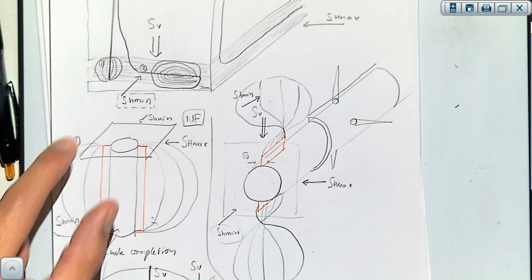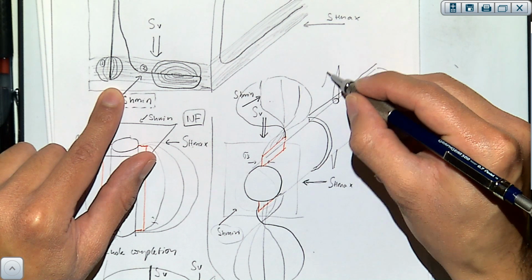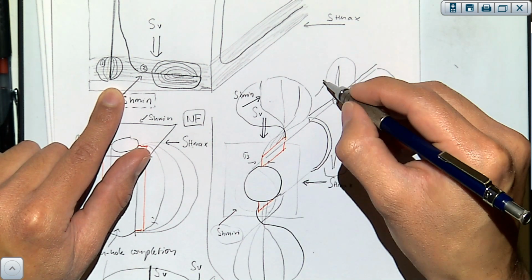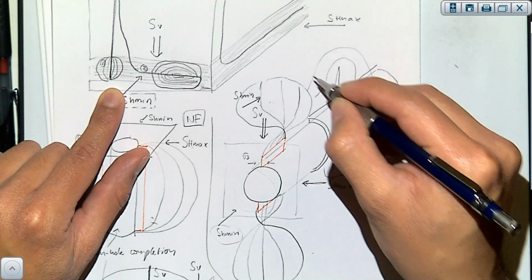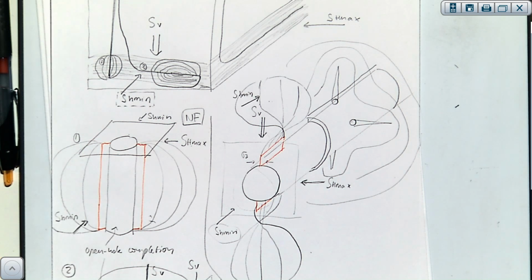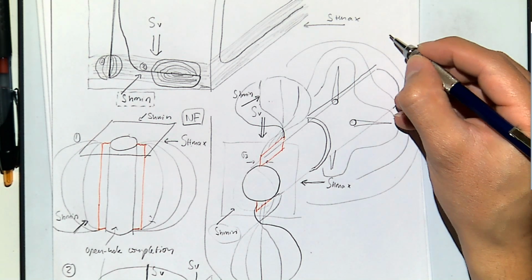So by having these perforations, a hydraulic fracture that may start something like this might grow into a large hydraulic fracture plane, which is perpendicular to the minimum principal stress.